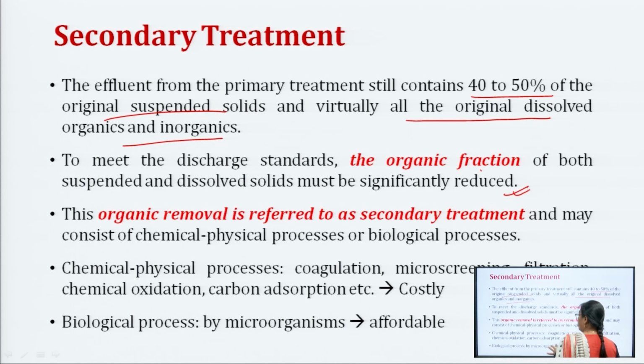Primary sedimentation removed a part of the organics, right, but the majority of the organic part is still there. So what you have to do is remove the organic fraction of both the suspended and the dissolved solids. This organic removal is referred to as secondary treatment, and may consist of chemical physical processes or biological processes.